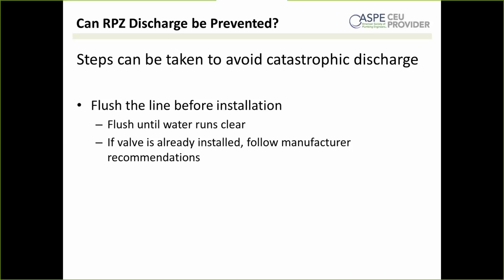For this reason, backflow preventers often fail their very first test after install. They get installed, you turn the water on, and they start dripping. Then no one is happy when the contractor removes it thinking it's defective, only to have the return rejected because the manufacturer didn't put that rock in the first check. I can tell you we definitely do not ship backflow preventers out with big chunks of concrete holding the first check open. So it's very, very important to flush that line until the water runs clear.